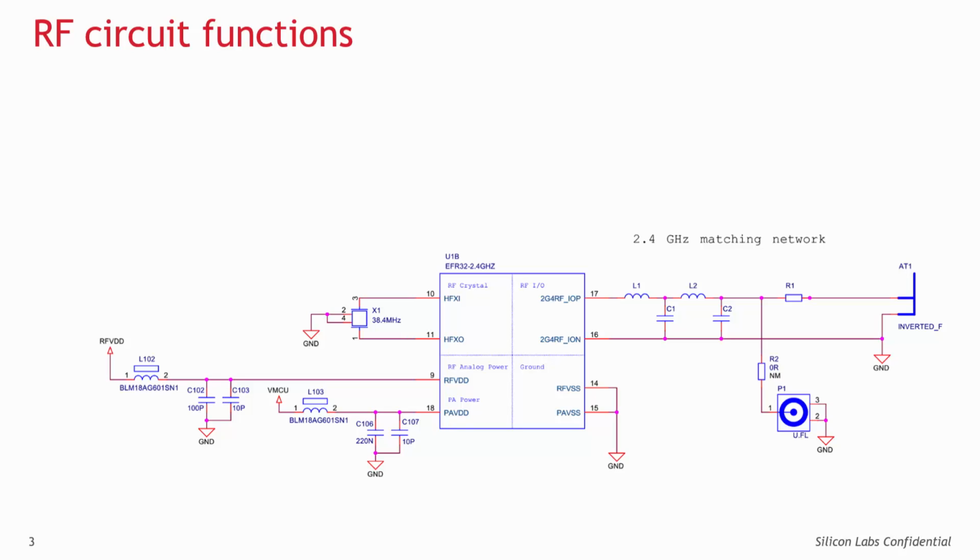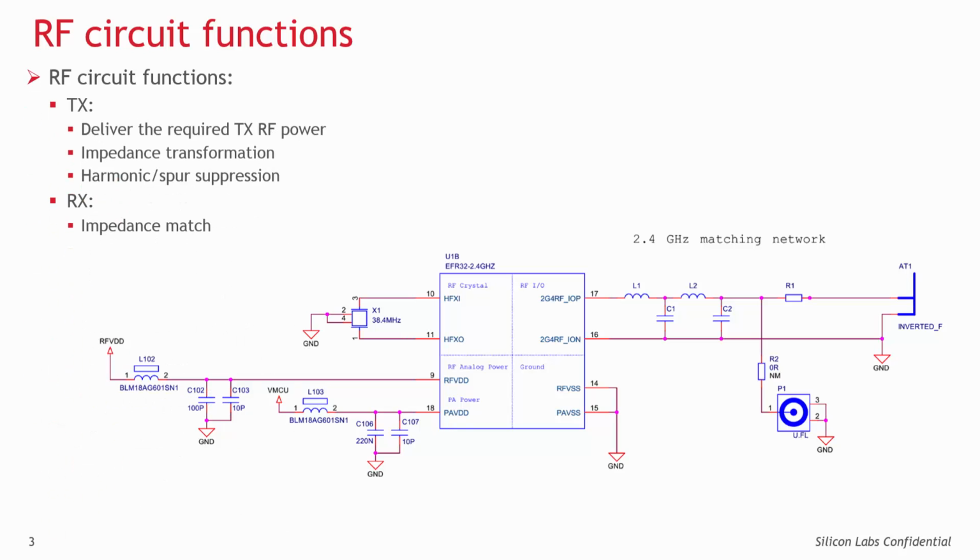The RF transmitter ICs can synthesize high frequency and high power signals at their TX output: the fundamental, its harmonics and additional spurious content. A part of this power is radiated, the other part is dissipated on losses. On the Silicon Labs reference design boards, the function of the TX matching is to drive most of the fundamental power into the antenna, thus to provide the required impedance transformation between the RFIC and the load. Simultaneously, for suppressing harmonics and spurs, a proper filtering network should be used between the matching network and the antenna. The matching and filtering is combined in one series L parallel C ladder structured network, which is also used for the RX side during receive mode.